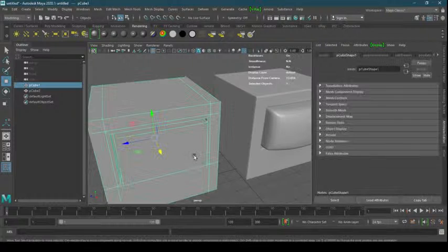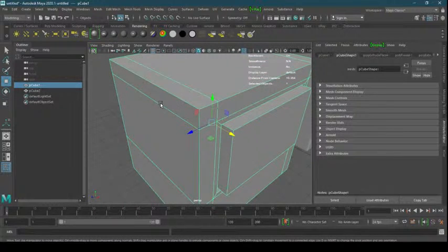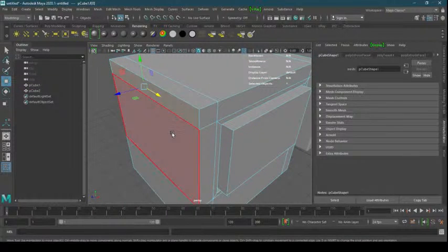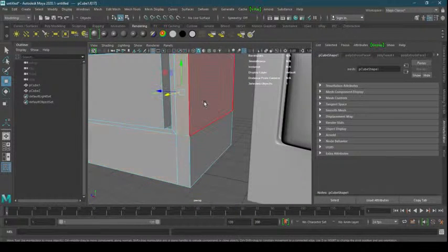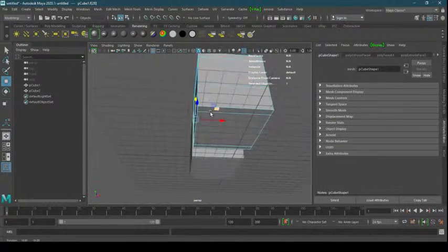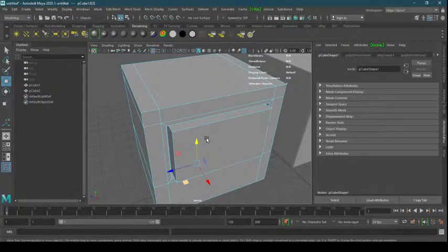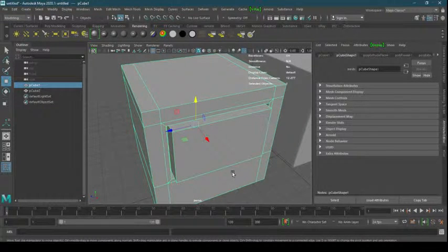Clear? And if you notice here, this is very low polygon. Can you see these faces? These faces are polygons. There are very few faces over here. If there are very few faces like this on my screen, when I'm done with the modeling, I have to apply the smooth modifier on it.